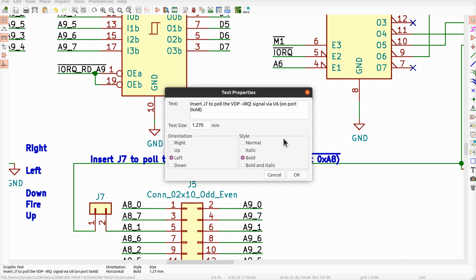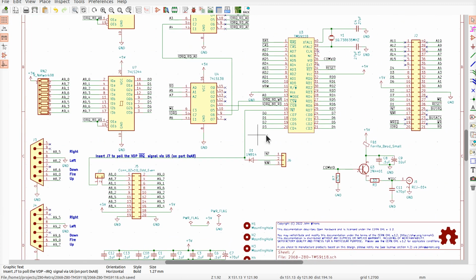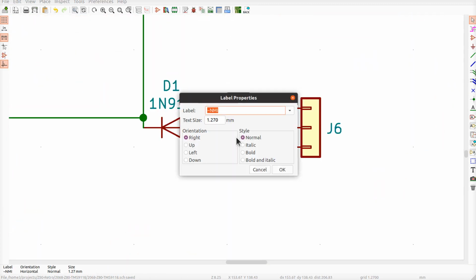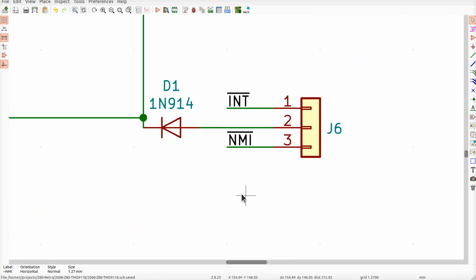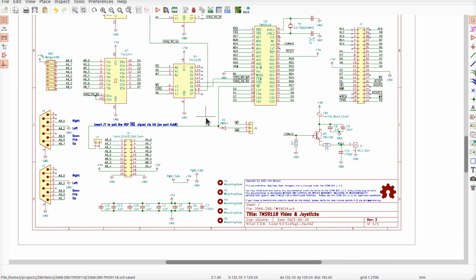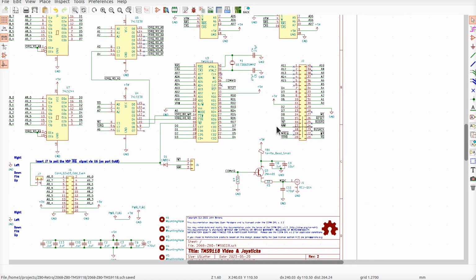I've noticed a lot of people, if you have a single word with an overline like I do here, will just put a single tilde on the left and leave it at that. And that's okay, but be careful because it may not mean what you think it does when it comes to matching other labels in this same drawing.